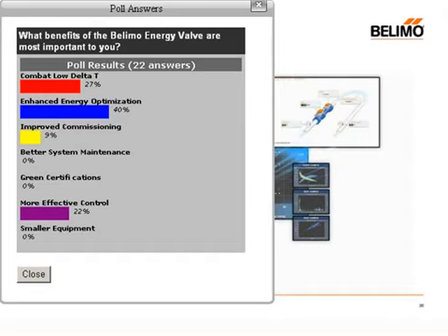Like I said, you're converting from having delta T being a dependent variable to being an independent variable, and you're just going to get system pressures as you need. I think they would both work very effectively together. You probably have to reset your pressure settings to work most effectively with it. Very good.